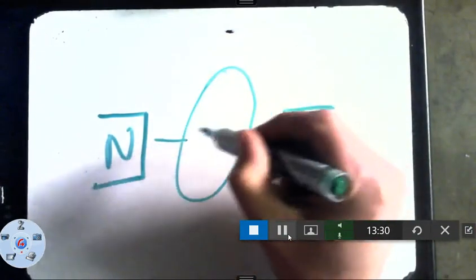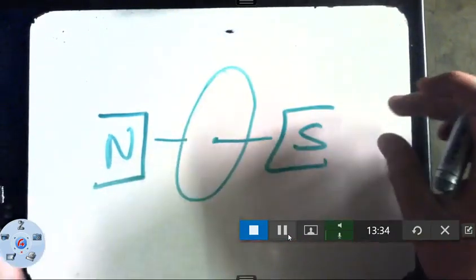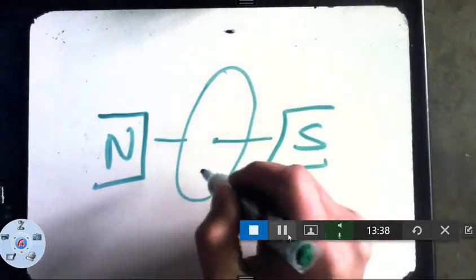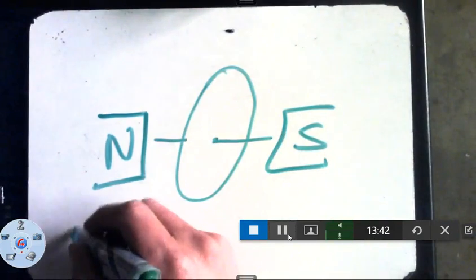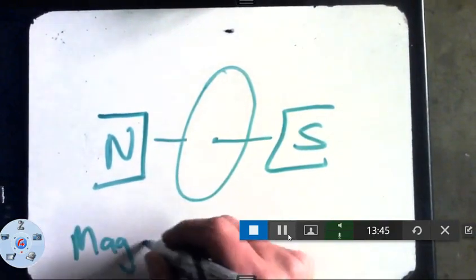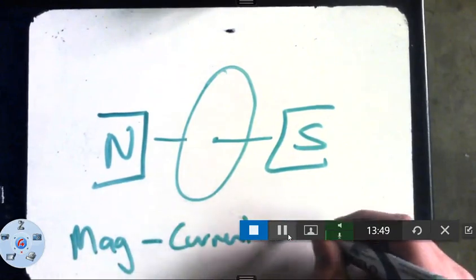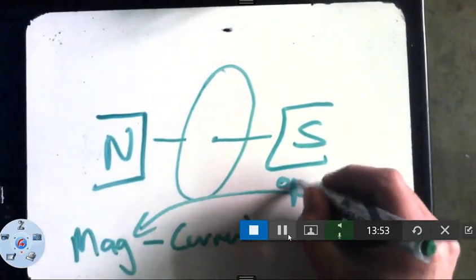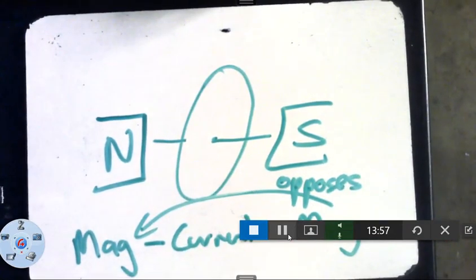Normally the disc would just continue to spin until friction stops it, but the moment I bring that disc into my magnetic field, it stops automatically. What happens is the magnetic field creates a current, and that current creates a secondary magnetic field that opposes that one.